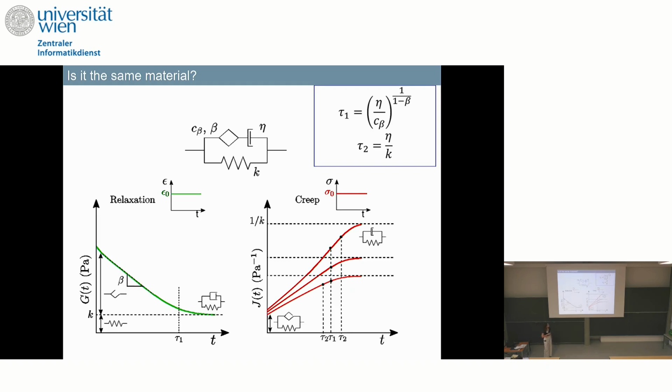When we go to creep, that becomes a bit more complicated because, as you can see, we can go from having just a plateau, so it plateaus, or it does have an inflection point before the plateau. And that's because now we have 2 characteristic times that play a role. Depending on the relative position of these 2 characteristic times, you can observe 2 completely qualitatively different behaviors.